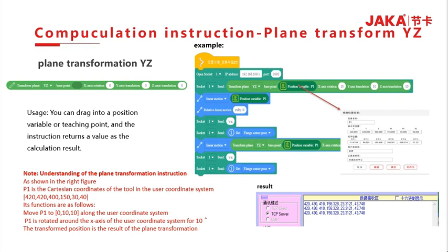The parameters are the y, z, and r axes respectively, and the socket sends the coordinates of the center flange position of the robot's end after the movement is in place. The robot moves linearly to the result position after the plane transformation. Then the socket sends the robot end flange center position after the movement is in place. The following picture shows the result received by the socket. We will see that the data received 3 times is the same.